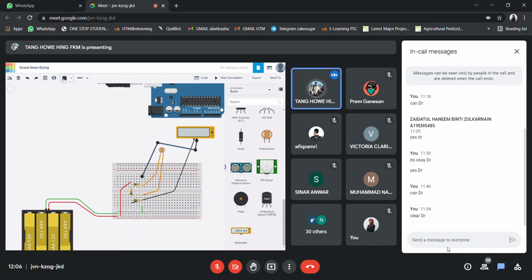All right, so this round we swap the VB and the VA. So right now it becomes positive here. Right now we are measuring VB minus VA, so we are going to get positive 2.98 volt. And then if we change, we are going to get 19.1 millivolt.